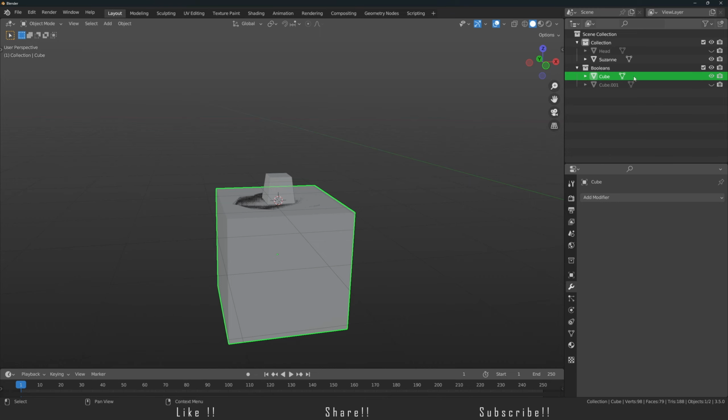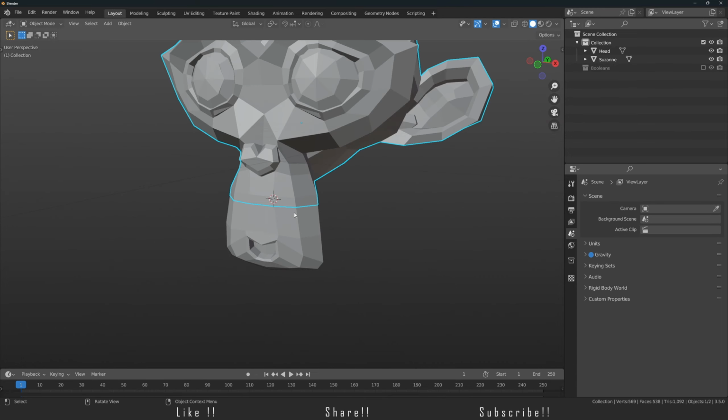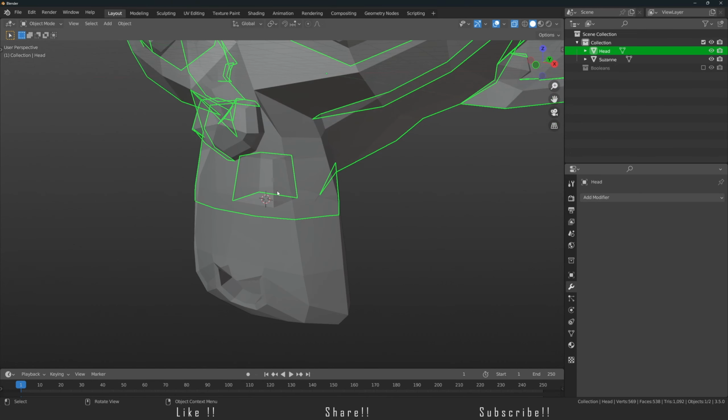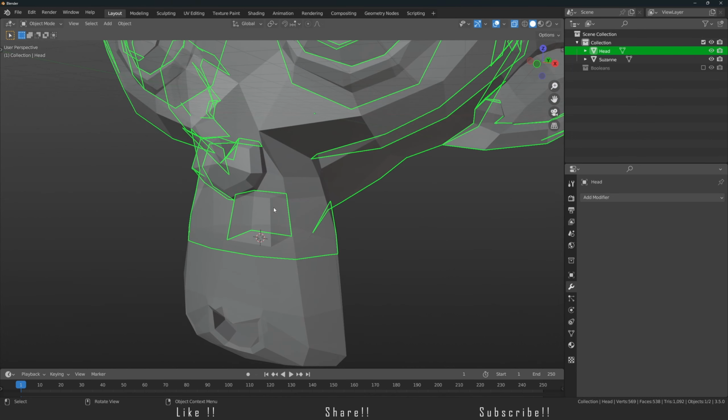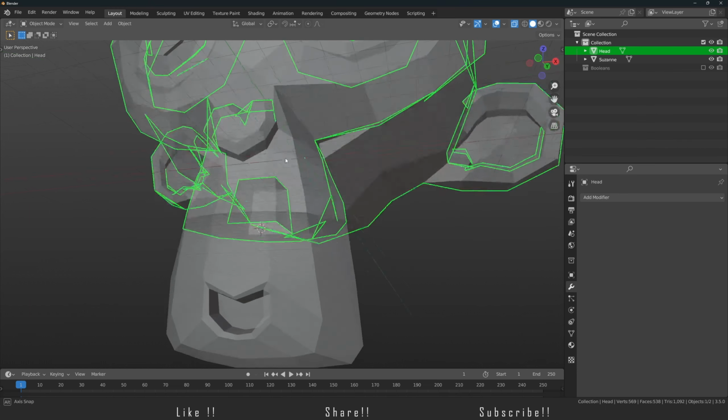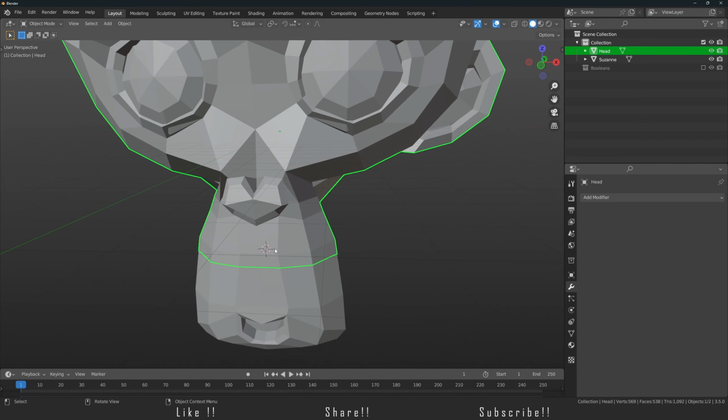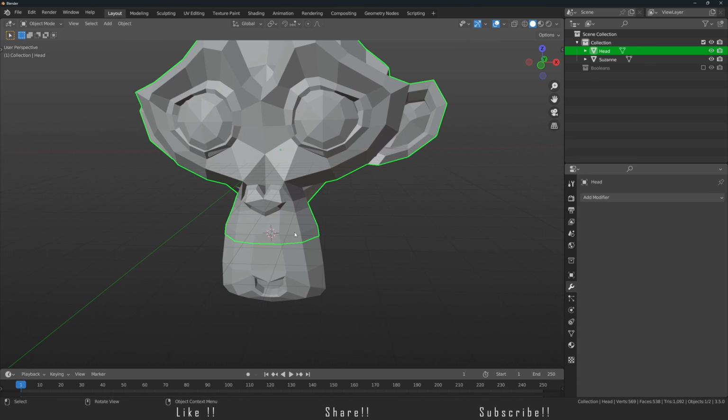Now you can see we basically have the male and the female key, and now I have shown you how to use Blender's tools, like Blender's Boolean tool, to create the keys. Now let's look at the second example. So let's just get over there.